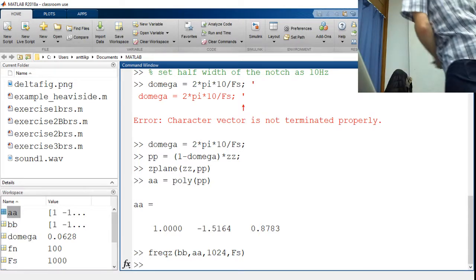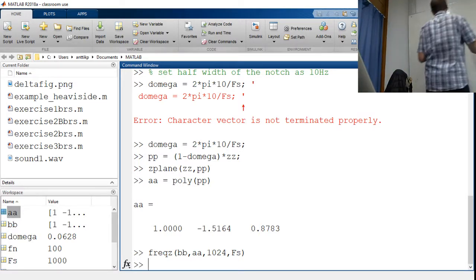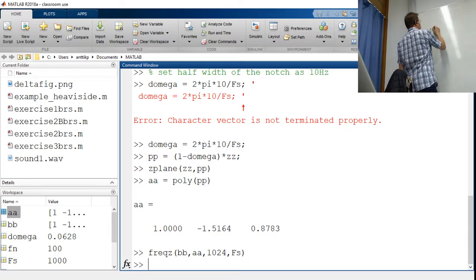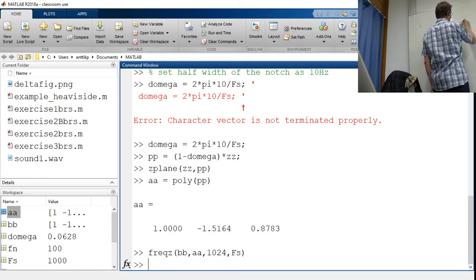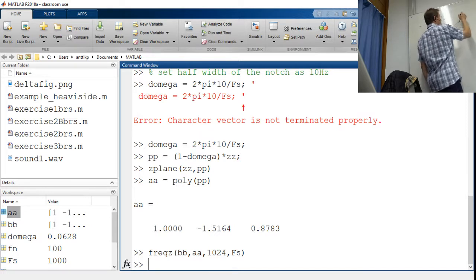But anyhow, you have a time-based signal coming in, and that goes into your amplification, or probably on this microcontroller unit, and then you have the sampling A to D converter. The sampling clock comes from somewhere. Make sure that you set up the sampling rate correctly. Follow the guidelines of what the datasheet gives.